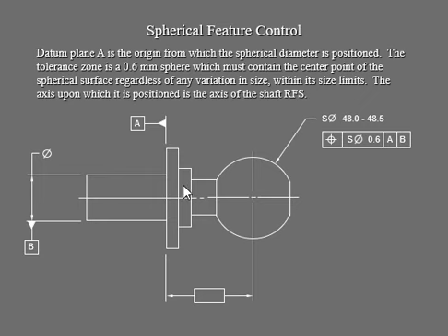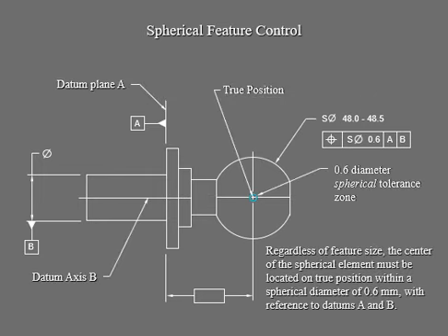And of course they're related to this flat surface. All right, so datum plane, your true position is right here for that sphere. And that is a 0.6 diameter, that is where we want to put that sphere in that part, so we're identifying this. And of course that diameter is the diameter of the sphere. Very different, two different diameters. How big is that? See that? So you can see how small this little thing is, the position.